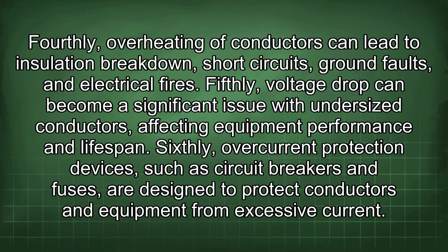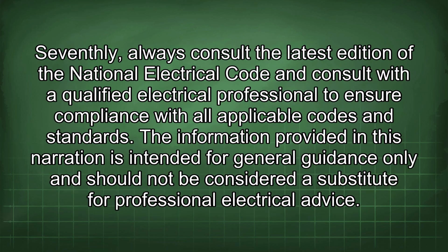Fourthly, overheating of conductors can lead to insulation breakdown, short circuits, ground faults, and electrical fires. Fifthly, voltage drop can become a significant issue with undersized conductors, affecting equipment performance and lifespan. Sixthly, overcurrent protection devices, such as circuit breakers and fuses, are designed to protect conductors and equipment from excessive current. Seventhly, always consult the latest edition of the National Electrical Code and consult with a qualified electrical professional to ensure compliance with all applicable codes and standards.